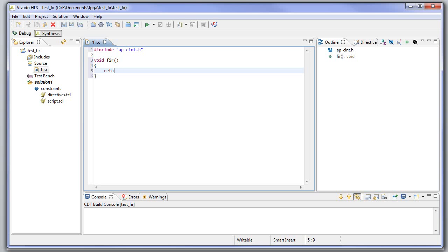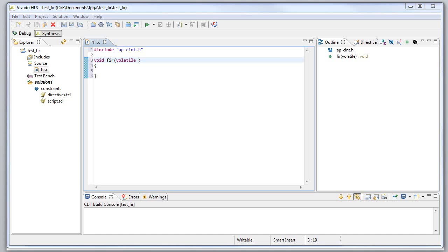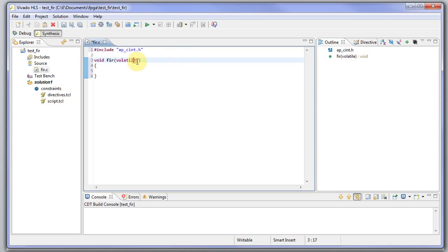What it'll have in it is the input, and they come from the ADC. It's an offset decimal format, and this will be the X. Oops, I did that backwards, didn't I? Sorry, I was just checking the datasheet. They are 10 bits. So we want a uint10 pointer X, volatile, and then a uint10 for the output to the DAC.